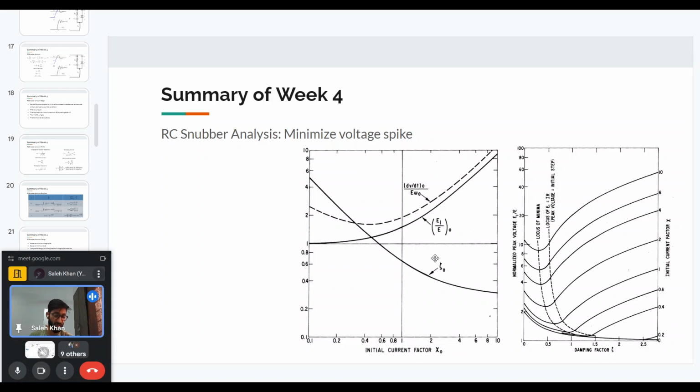So the LCR meters or the impedance analyzers that we have cannot measure the parasitic inductances to this value. So the other option is you have to determine it using analytical methods.